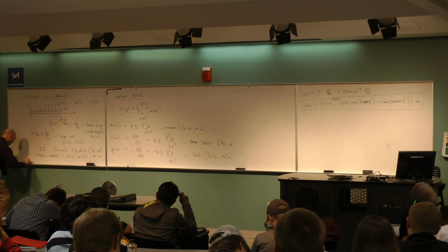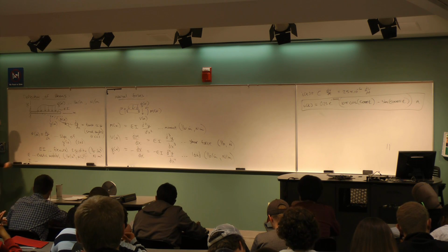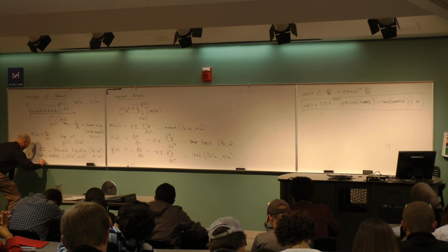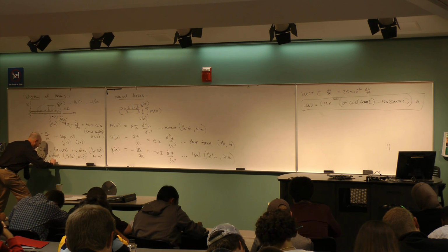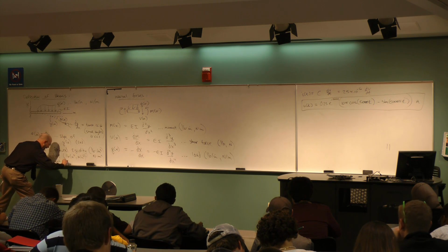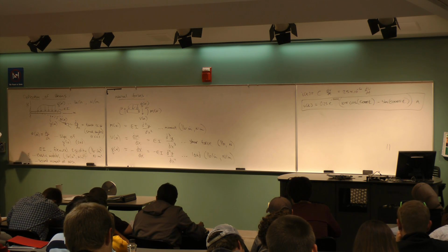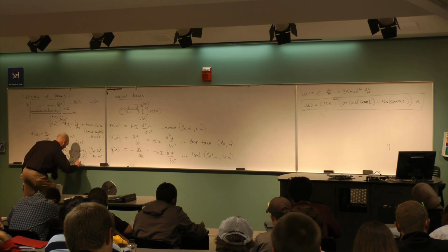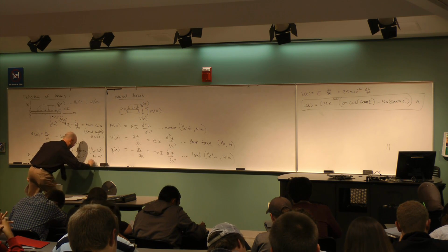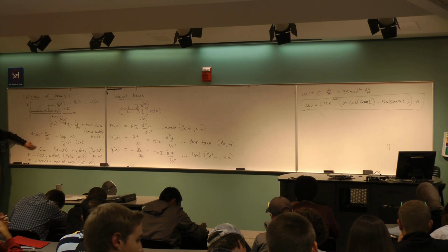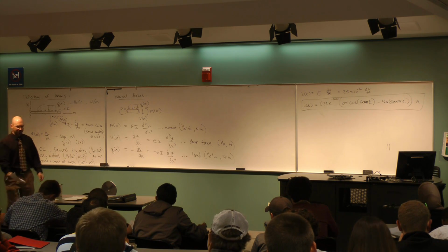And finally, I is actually something, if you've had calculus, you may have seen before. This is the second moment of inertia, also called moment of area. And if you've had some calculus, turns out the definition of I is in terms of an integral. So we'll talk maybe a little more about that later. Inches to the fourth or meters to the fourth. Okay, so here's the thing. The I has to do with basically how beefy the cross section is.